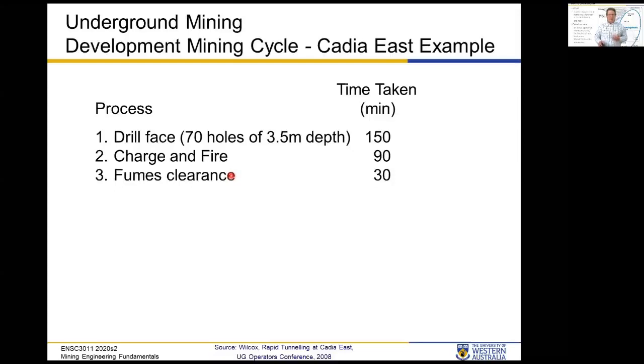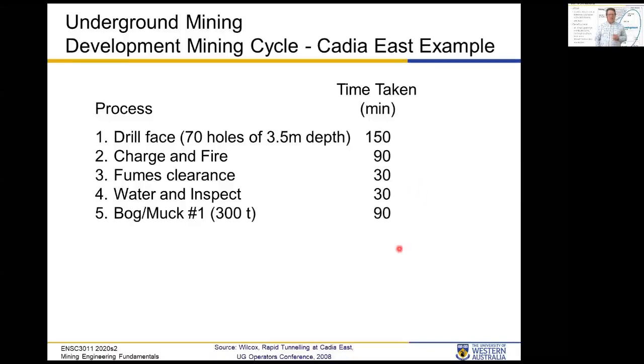Fumes clearance, 30 minutes till they're allowed to go back in. This is where they sprayed water on the face to inspect it. So that took half an hour, safety. And then remove the broken ore. Then do hydroscaling and shotcrete.